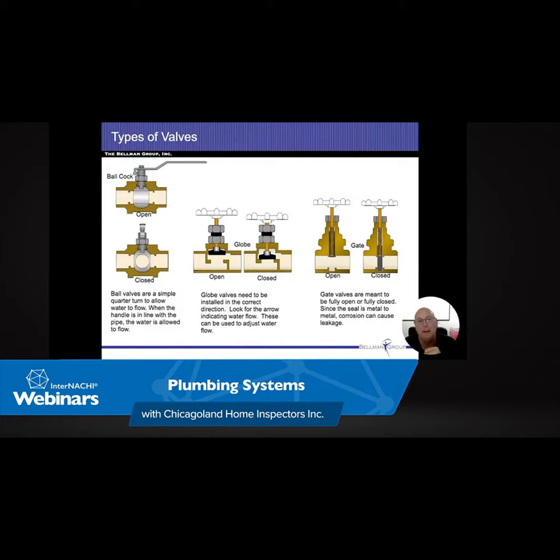So make it clear that the only thing that goes in there is feces and toilet paper, not even wet wipes, all right? Even if it says it's disposable and safe for sewer systems, those will get in there and gum the works. And then if it just turns into a glob of mud and doesn't get disintegrated, then that pump is going to overheat or bind up, and then you're going to end up replacing it. And you don't want to go into wastewater tanks to replace a pump. So the longer we can make this thing last, the better off everything would be.